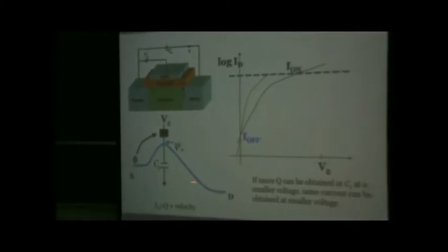So that's the idea: if I can put a ferroelectric material on top of a MOSFET channel, use it as a gate insulator, and be able to stabilize it right there, right at the point where it is negative, it gives me negative differential capacitance, and I can basically reduce the supply voltage.